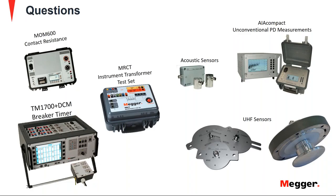It's going to have to be on a flange, and likely you should have a flange that either is made up of epoxy in the middle, as we saw, or, even if it's metallic, should have that nameplate section that's typically filled in with the epoxy. These don't really require you to measure anywhere particular, which is kind of piggybacking off of the other question of the interruption by circuit breaker or disconnector, where you have the ability and the freedom of moving these sensors, as these are online measurements.